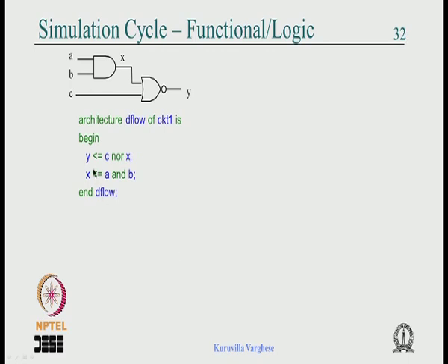So the next simulation time will be 100 plus delta. This is computed and then Y is assigned at 100 plus 2 delta, okay. When everything is done, you look at the right hand side, there is nothing to do, it is stabilized. At that point delta is made 0, so you get the correct X and Y, there is no issue.